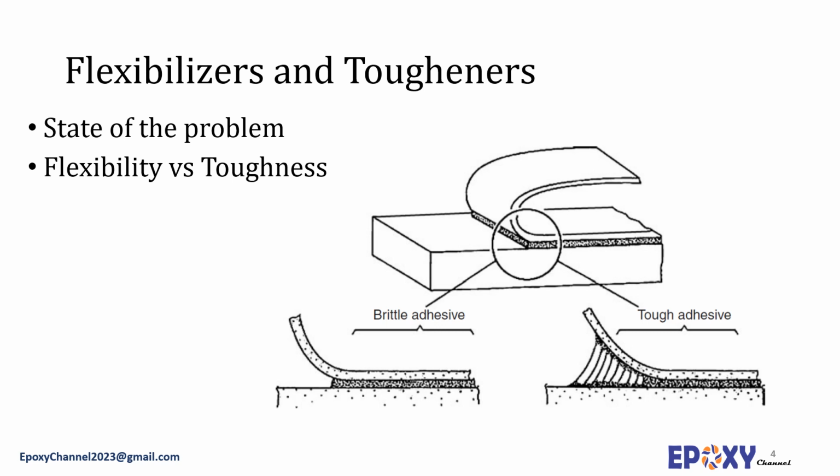Flexibility is primarily characterized by a material's elongation. Flexibilizers in epoxy systems work by allowing the material to deform under stress, and the higher elongation yields higher peel strengths. In other words, flexibilized adhesives reduce mechanical damage by lowering the modulus and increasing elongation via plasticization. This increase in flexibility is mainly due to decreasing the crosslinking density of the cured adhesives. However, decreasing the crosslinking density results in lowering of certain properties such as tensile strength and glass transition temperature.